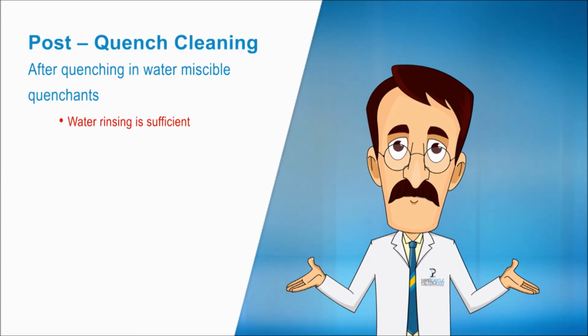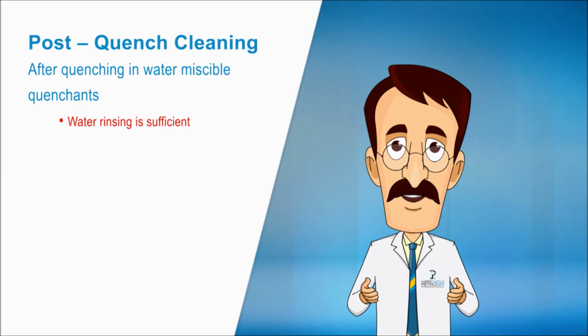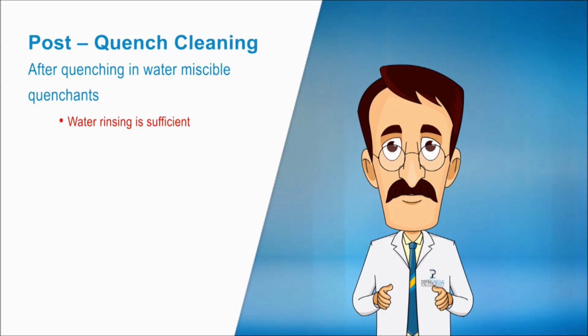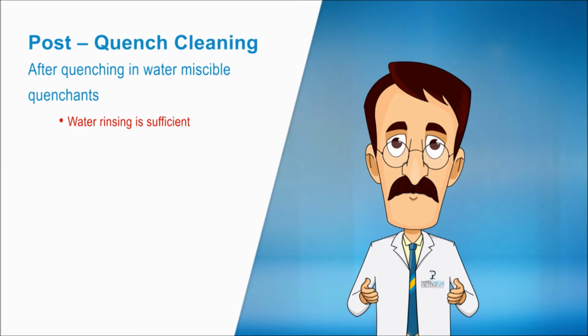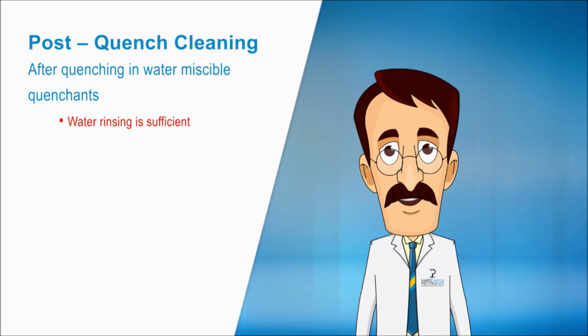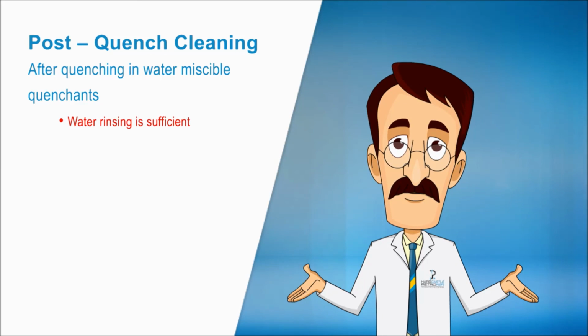Hardcastle Petrofers quenching oils will produce hardened components with a bright finish, provided, of course, there was no prior surface oxidation. The components are suitable for further treatment, such as electroplating, without problems. Oil residues do not burn into the surface of the metal and therefore can be easily removed.